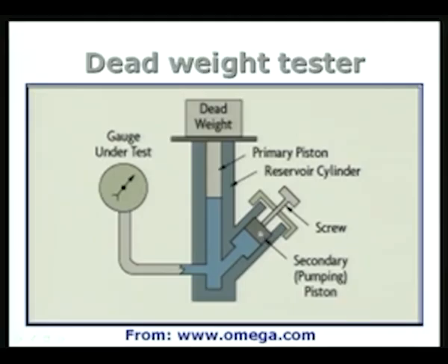This plunger is going to go in and out and increase or decrease the pressure, as the case may be, and there is a dead weight, and there is a piston on which the dead weight is placed. This whole thing is vertically oriented, and if the dead weight is just floating, that is, if the oil pressure is such that the pressure exerted by the dead weight on the piston, which is simply given by the weight placed on the piston divided by the area of cross section of the piston, that is the pressure.